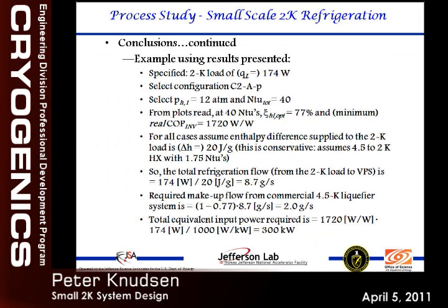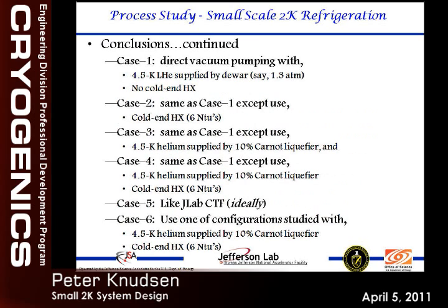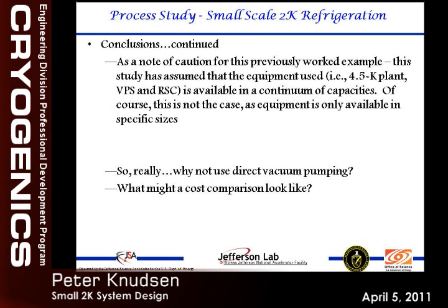And I worked through an example here on this slide. You can work through it if you want. Basically what I did was I took that data and worked through an example on how to use it. But the caution note that I would give is that you can calculate a number, but you may not be able to find a vacuum pump that fits precisely that size. And that's typically going to be the case for compressors and vacuum pumps. They don't come in continuum sizes. So there is a note of caution to that.